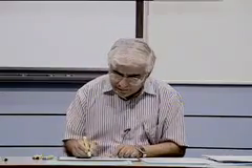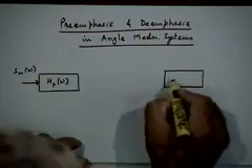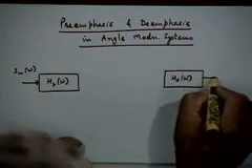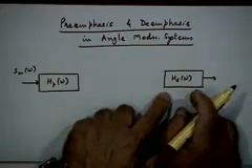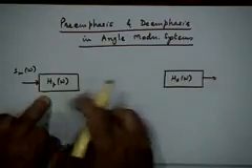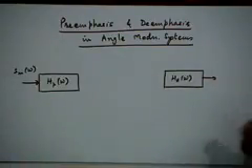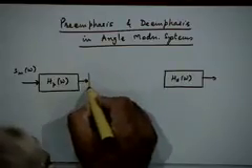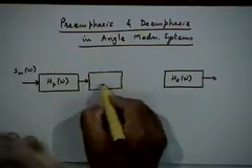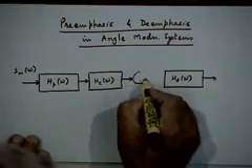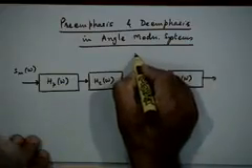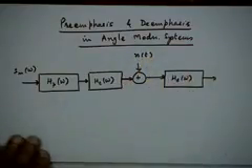So you have to carry out the corresponding compensatory filtering at the receiver, which is called the de-emphasis filter. The complete communication system will have a pre-emphasis filter at the transmitter and a corresponding de-emphasis filter at the receiver, so that the combined product of these two is constant. To keep the discussion more general, you may also have a channel with some transfer function H_c(omega), and of course you have noise, which is the additional complication. That's the complete picture.